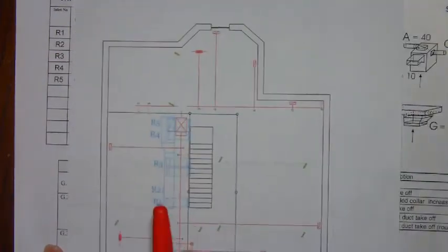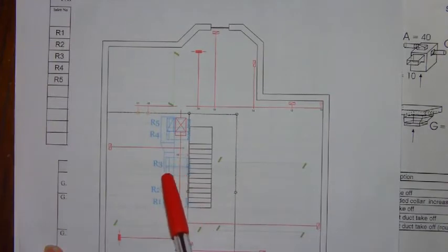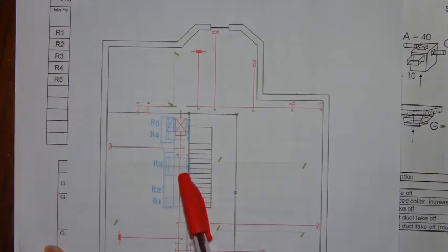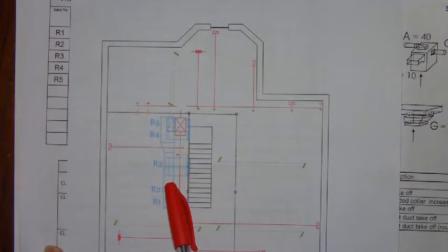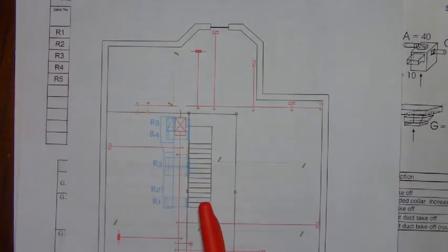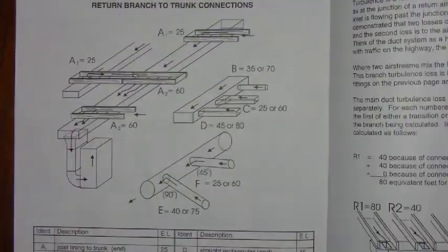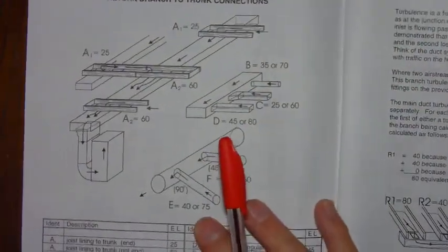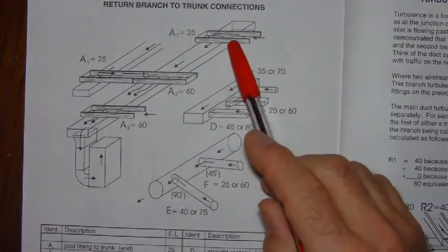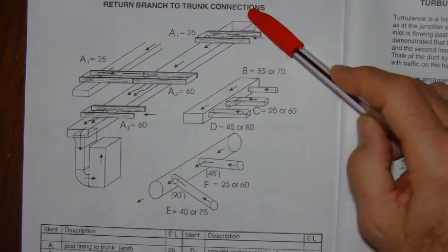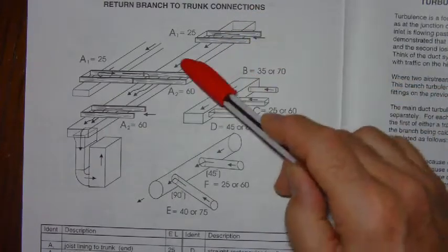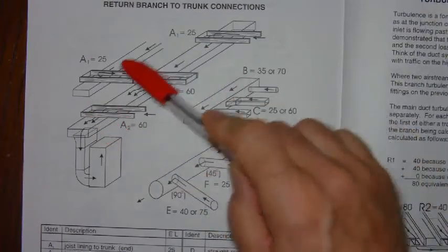However, we do have a duct to joist, or in this particular case it's more accurate to say joist to duct. The air is flowing through the joist into the duct, and so we need to assess the equivalent length at that point. This is where you need to determine, is the return air entering the duct at an extreme end, or is the return air entering the duct somewhere in the middle?